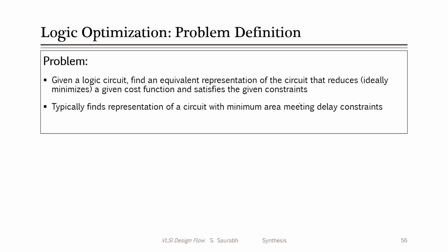At this point in time, the area will be minimized, and the timing and area estimates are based on just gate count and depth of the logic. We mostly do the area optimization at logic optimization just after RTL synthesis. We have not used the technology library, so the timing of the circuit cannot be computed accurately, and that's why we don't do a rigorous timing analysis and timing optimization of the circuit at this point of time.